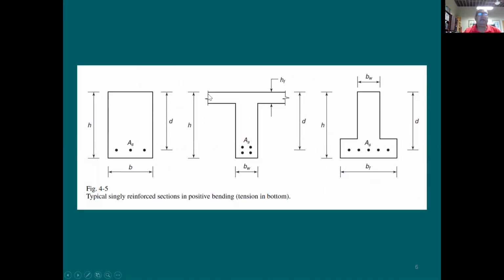All right, I'm looking here for the potential reinforcement that I'd like to put here for the concrete slab. Here's a rectangular section. This is the one that we are used to, this one that we have seen. And we say before cracking, you don't want to really look at this AS. And AS, as you guys know, is going to be the total cross-section area of the reinforcement bars. So let's say if I have 3 number 9, and for number 9, the cross-section area of 1 rebar is going to be 1 square inch. I have 3 of them, it's going to be 3 square inches.